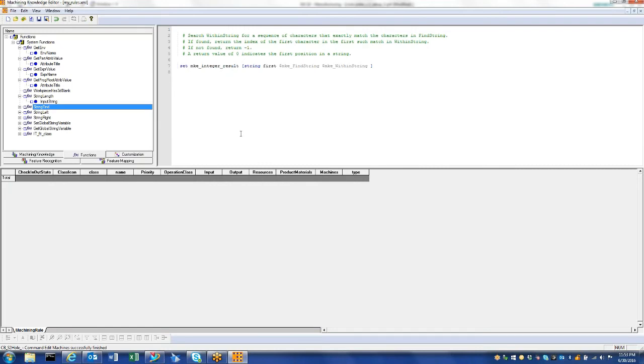And if you're running CAM Express, where NX isn't your primary CAD system, we can take attributes from the other CAD systems' 3D models. For example, if an M10 in CATIA always shades that feature in red color 157, then we can set rules in here that state whenever red number 157 is seen on a part, that is always going to be an M10 hole. And we can set up the logic so that it pulls the center drill, tap drill, and tap for the M10 hole. And that's how the find features and create feature processes work.